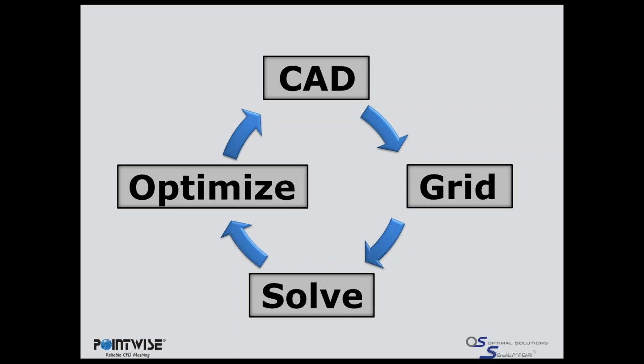The other thing to keep in mind is that you now no longer can guarantee that the changes in the solution and the objective function value are coming from the changes in the parameters for the CAD, or if they're coming from the changes to the mesh, okay? Because we know that the mesh is going to influence the solution, and if we have to remesh each design, it's going to change for each design.